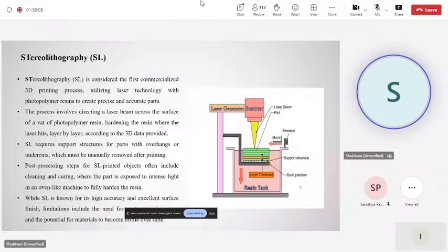Once the printing is complete, stereolithographic printed objects typically undergo a post-processing step in which any extra layer or support is removed. This post-processing cleaning process involves removing excess resin or support structures, to ensure that the part surface is very smooth and free from any imperfections.